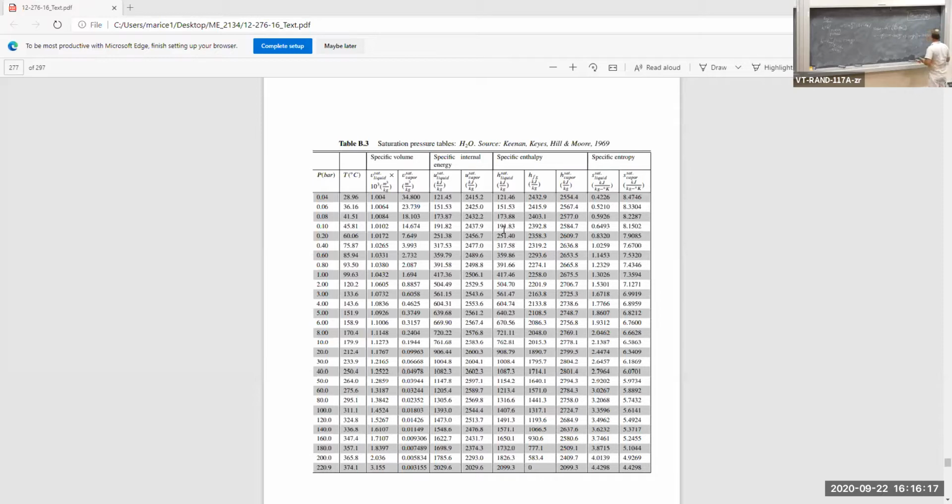I'm going to convert that into megawatts. 1 megawatt is equal to 1,000 kilowatts. So the kilowatts cancel, and I've got to divide that by 1,000. And I get 10.18 megawatts. So the shaft work supplied by the turbine is basically 10.2 megawatts. That's how much power is being produced by this thing.